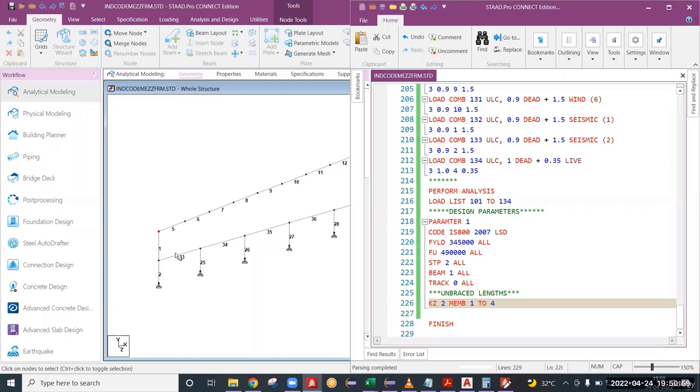Can you go through the effective length factor table? Someone has asked. One end is pinned, and the other end has translation allowed, rotation fixed. Rotation fixed means moment is not allowed to release. So what is the factor there?